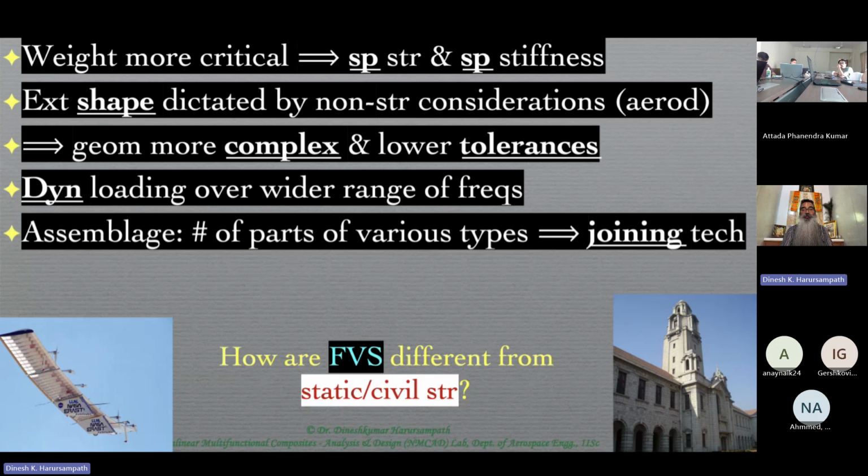Yet, because we are looking at fairly large passenger aircraft or aircraft which have other stringent performance requirements like very high speed, carrying very large payloads, flying over long ranges or requiring a lot of endurance, the complexity of the loads and the way they vary come into the picture, and therefore you might have a few joints, but not as many as in the past.